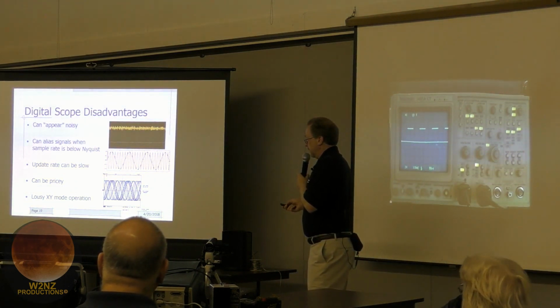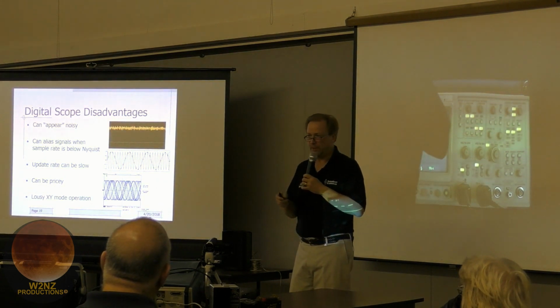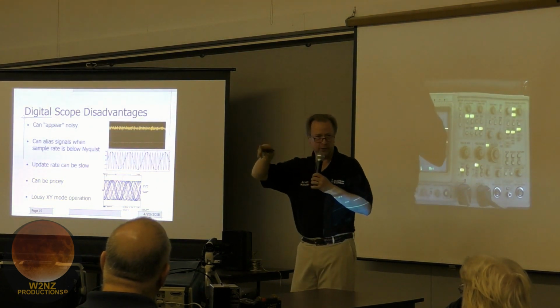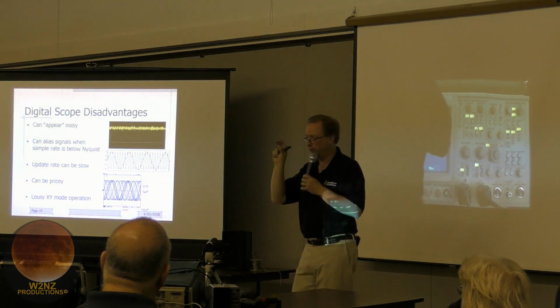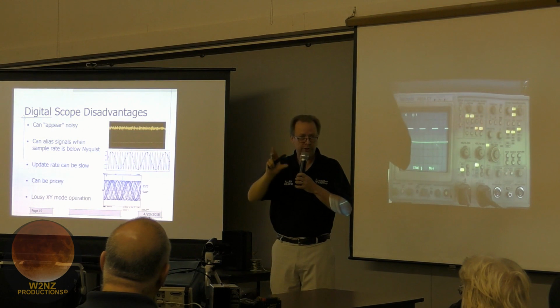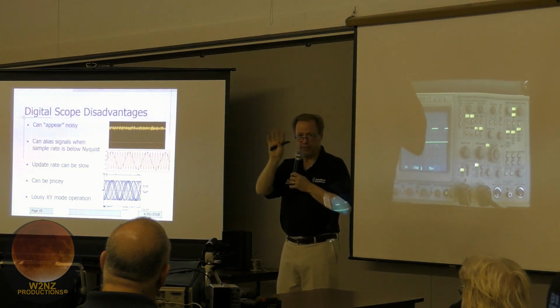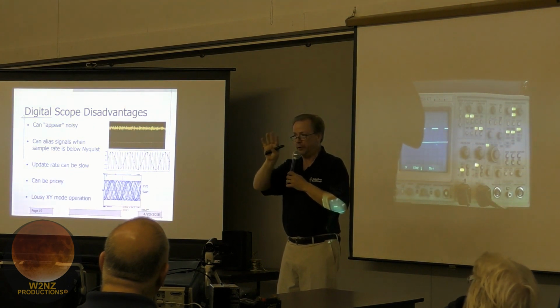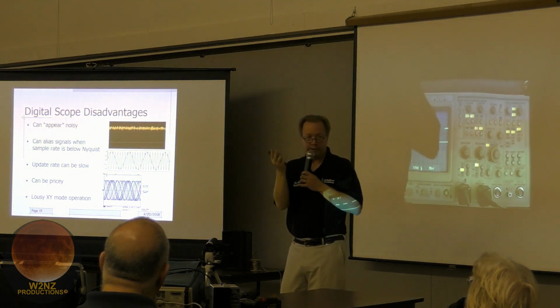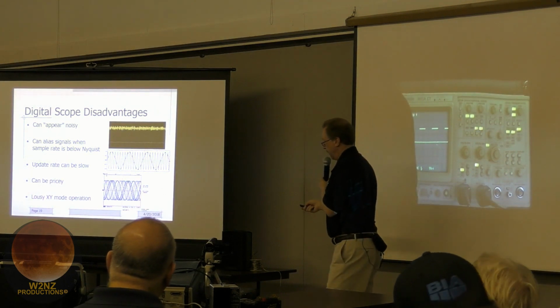Now aliasing is, like I said, what happens if you're sampling signals at too low of a frequency. And this is that wagon wheel effect, where the wagon wheels turn backwards because whenever the camera captured a screenshot, it captured the wheel in a different position. The wheel's rotating really fast, but we're sampling it fairly slow. You might capture it in a different spot that makes it look like the wheel's going backwards when you play those frames back together. This is what it looks like graphically.